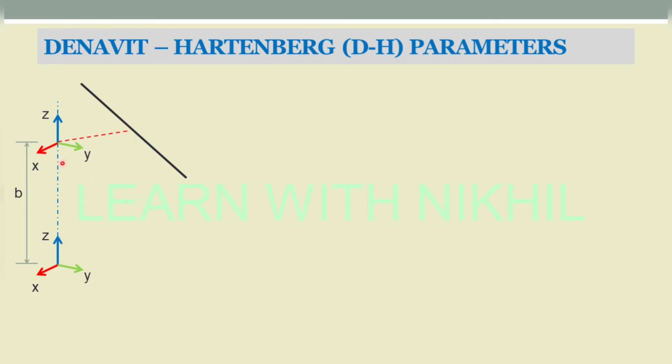First we have to extend it to a height of B. In some books it is denoted as D, here I am considering B. So it is transferred to a height of B. This transfer is written as translate Z B, till the intersection of the Z axis and the common normal, and this is called the joint offset. So this B is nothing but the joint offset.